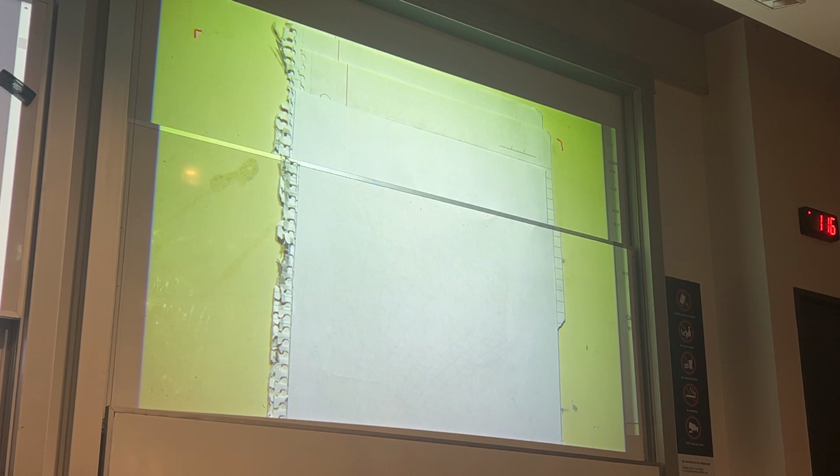So you're given 3 diagrams here. So we have this first diagram on the left, so we have compressor, combustion chamber, gas turbine, and then where we reject our heat, and in this case, where we reject our heat is actually our boiler for our Rankine cycle. So we've got a pump, a boiler, in this case our heat's coming from our gas turbine, and then we have a steam turbine, and then we have a condenser. So these cycles are linked together, and you can see that again in our entropy temperature graph.